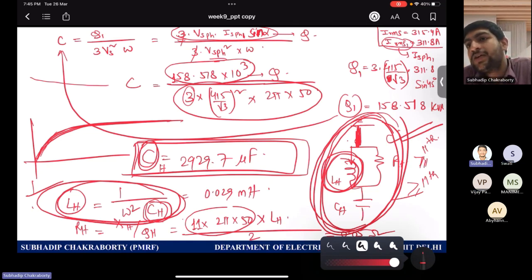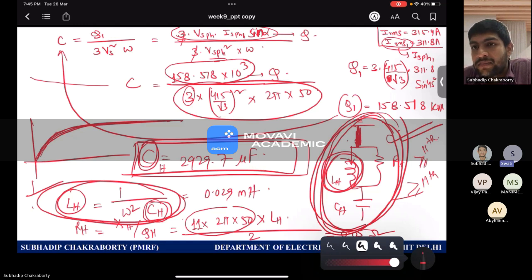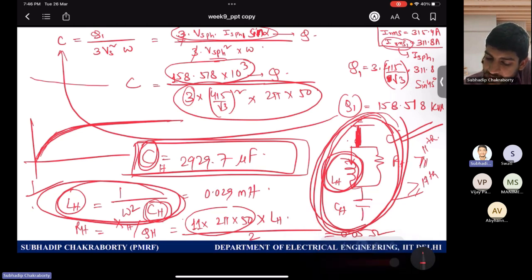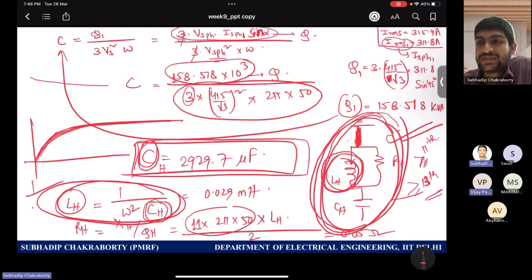But in this problem, we are only giving in general, single tuned filters are for lower harmonics, like 3 and 5. Not necessarily, they may be for higher order, and I may also extend it up to 13th order HPF. It depends on the application. If you need specific attenuation of some harmonic component, it is better to go for single tuned.